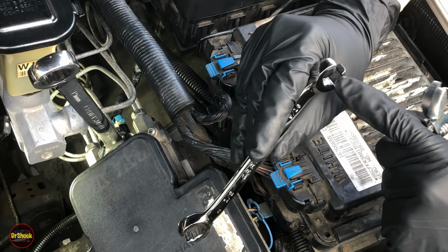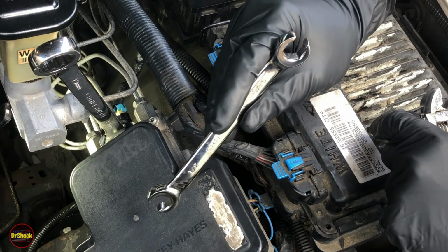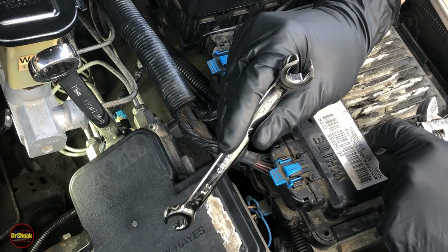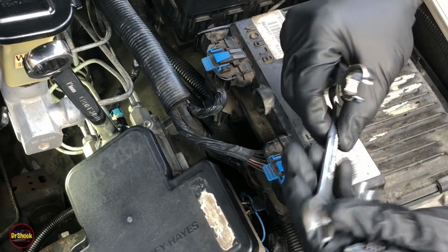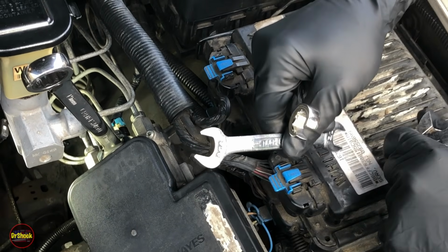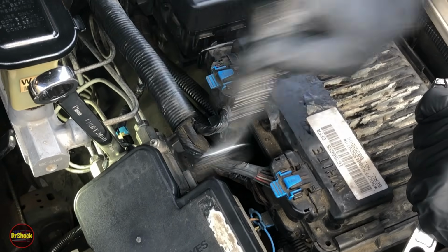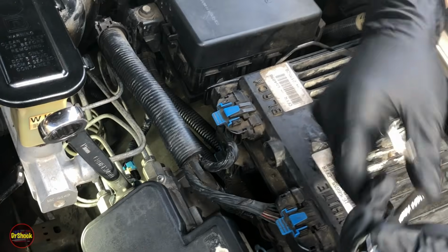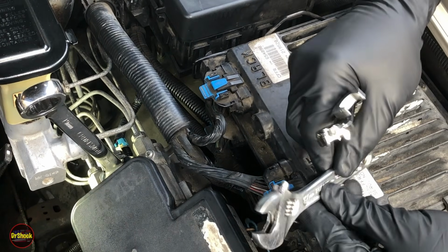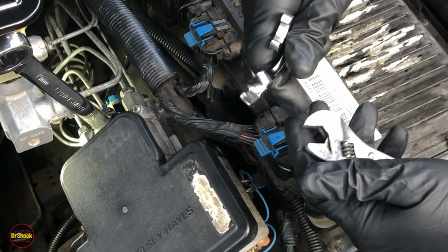That line wrench has the ability to cover more flats than an open-end wrench, and this is what we're going to use to break the torque as well as initially tighten down the brake line fittings. It is good to have a 9/16 open-end wrench. This comes in handy for the really quick, repetitive unscrewing and screwing of the fitting once you've got the torque broken. Similarly, a small adjustable wrench is also helpful for speeding through some of those steps.